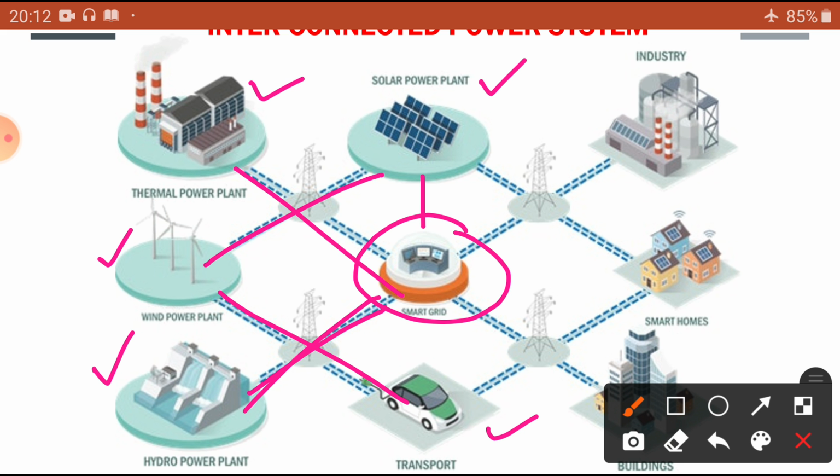Whereas in the rainy season, we can choose the hydropower plant as the base power station. At that condition, we can use the thermal power station as a peak power plant. As per our convenience, as per the available fossil fuels and water available in the dam, we can manage optimally as per requirement.